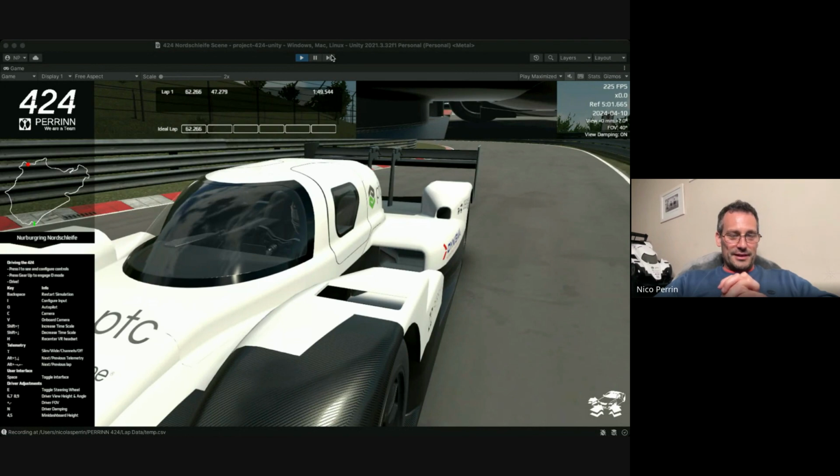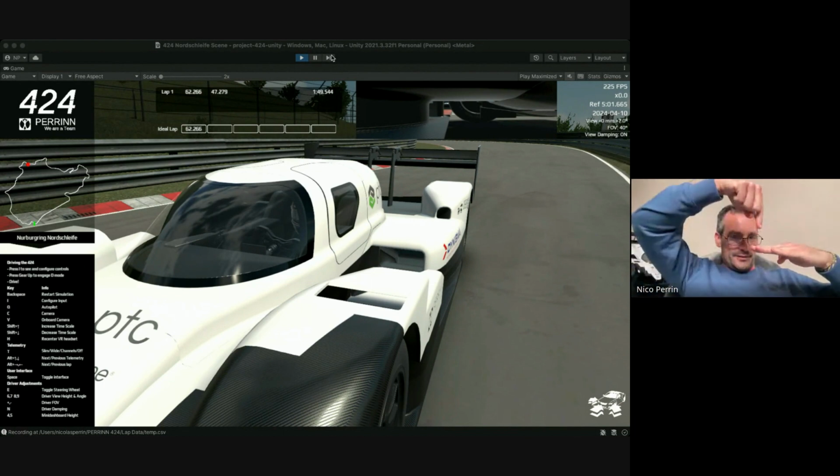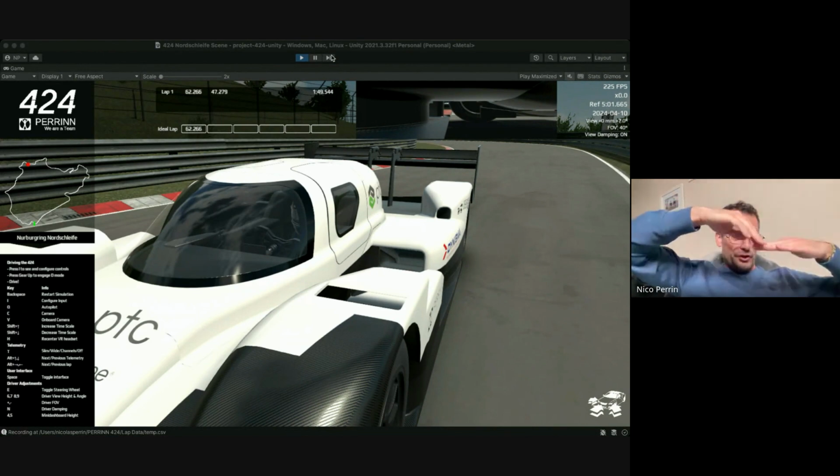The reason is the flap itself. When you go over bumps, it's like you're shaking the car, and the mass of each part matters at that point. The flap is in carbon, it's extremely light. It only weighs 1.5 kilos. And it's controlled by a hinge, and by this vertical rod with the spring. And what's pushing on it is a lot of aerodynamic load.